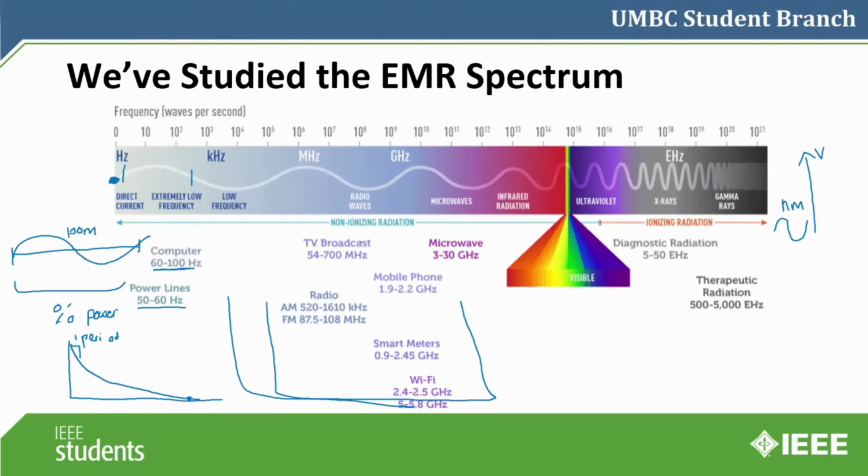Because this we found is the optimal space to transmit data. Because we get enough distance and we also get a high enough frequency that we can actually put data on it. Because remember, we want the wave to oscillate multiple times for each symbol that we transmit. So if this is 101, the symbol that we're transmitting, we want the wave to have a high enough frequency that it oscillates many times in each of these symbols.